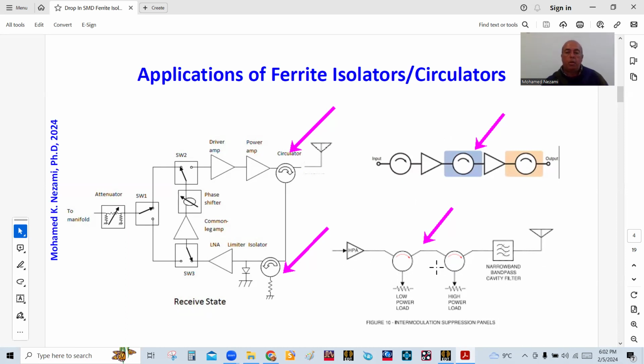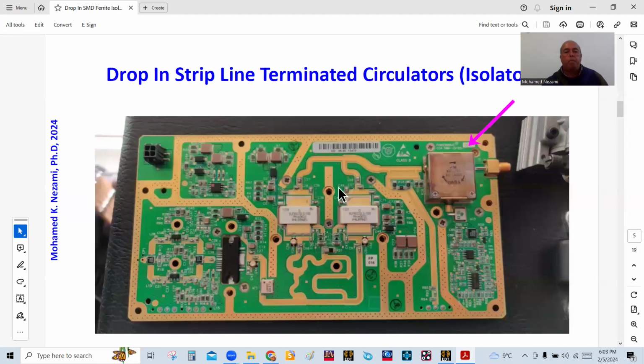And this is another one where you can do the transmit power amplifier isolation. In this example that I grabbed, somebody was illustrating how you can use two of these isolators if you want more isolation. So you get more insertion loss, but you get more isolation because the signal leaks in here, reflects back, and gets absorbed in here. If a certain portion comes back and you want to attenuate that even more, use another isolator. So it goes in here and then in here, and very little leaks back.